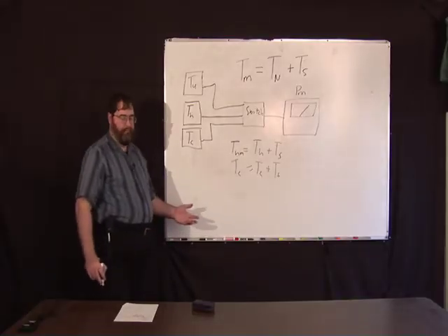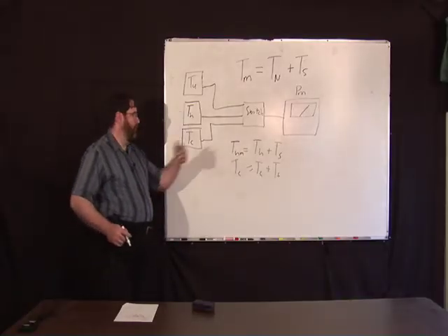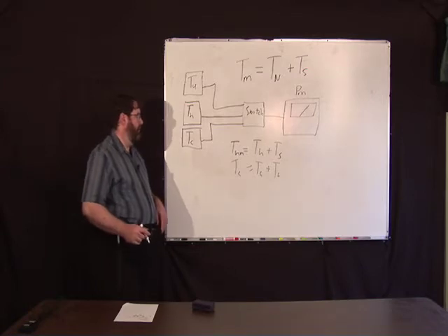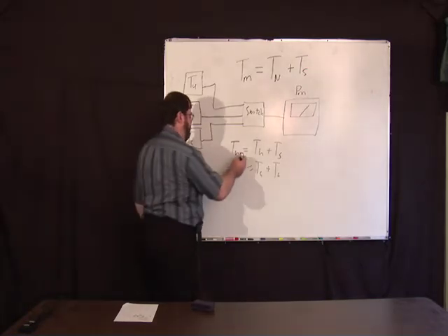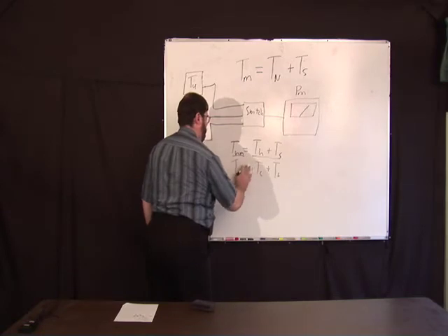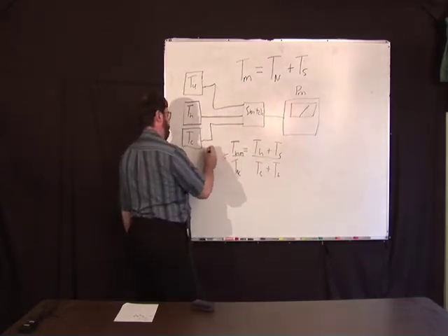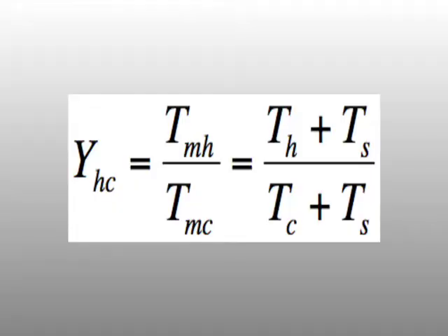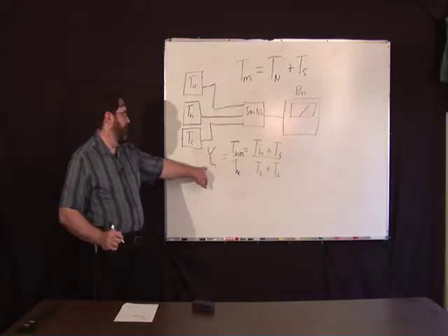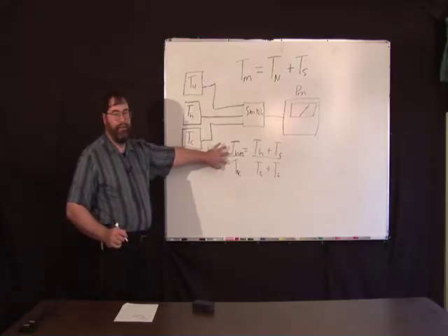What does that get you? Well, in order to find the system noise temperature, you can just divide these two measurements, and you get what's called the Y factor, just for historical reasons. The Y factor is just the ratio of the measured powers.